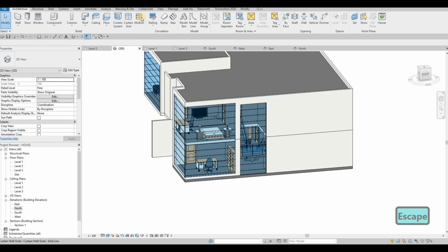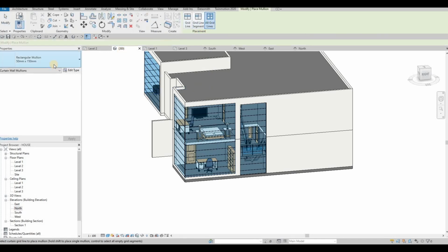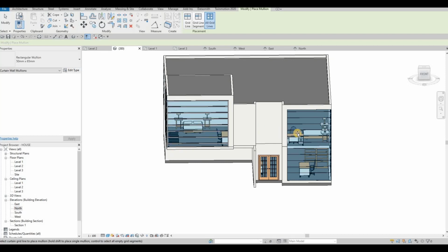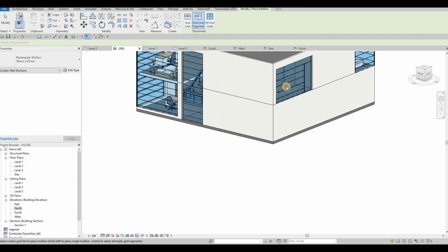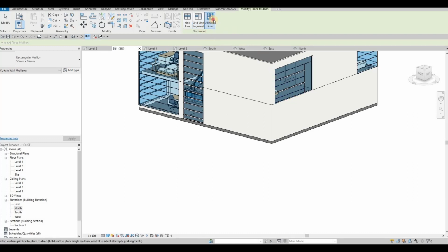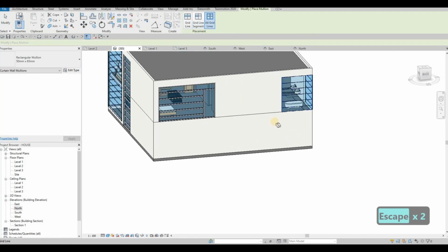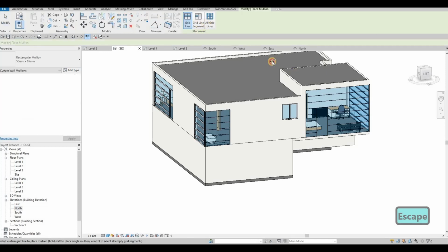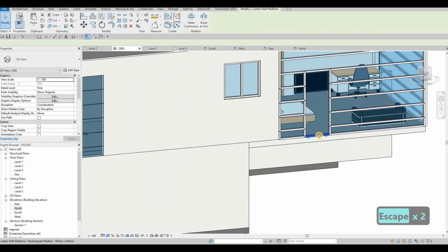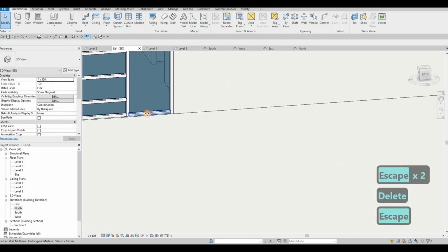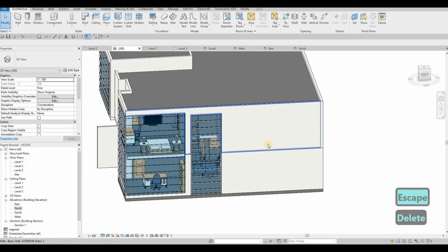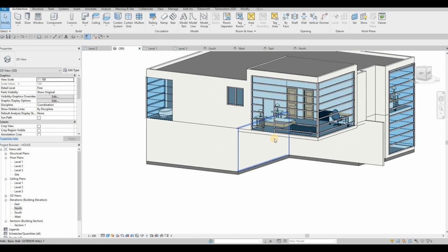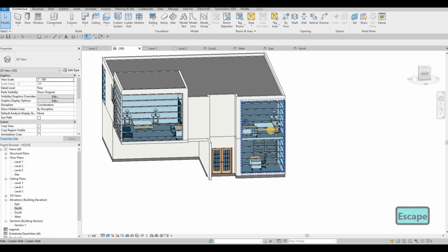So now let's add in our mullion. So I'm gonna click on mullion, all grid, but we're gonna use the 50 by 65, and then just simply add those ones right there. All grid. There we go, right there. You want to make sure to delete the bottom if you have a door. Obviously, you don't have mullions there. As you can see, it looks good.